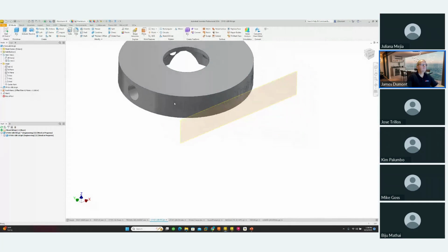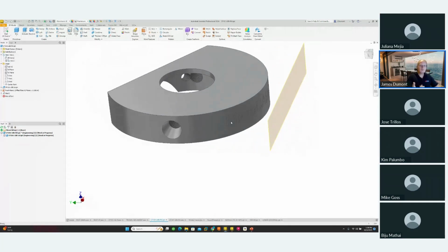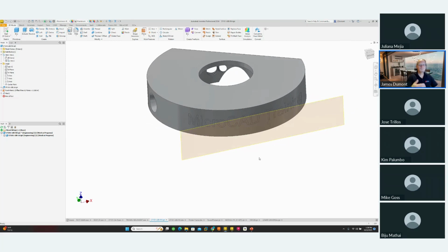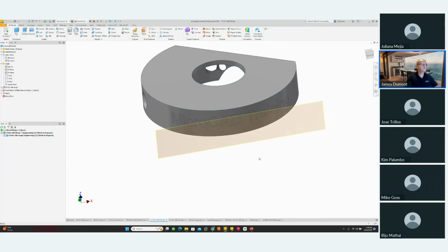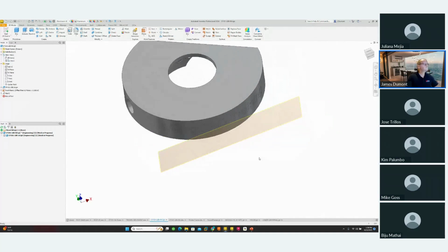But this is not embossed. This is not engraved. It's marked. And then if you do your export, that'll go out into your DXF file, and it goes on a specific layer, and it's really useful for doing your engraving, text, part numbers, things like that in your components. So the mark feature is relatively new, and I think it was 22.